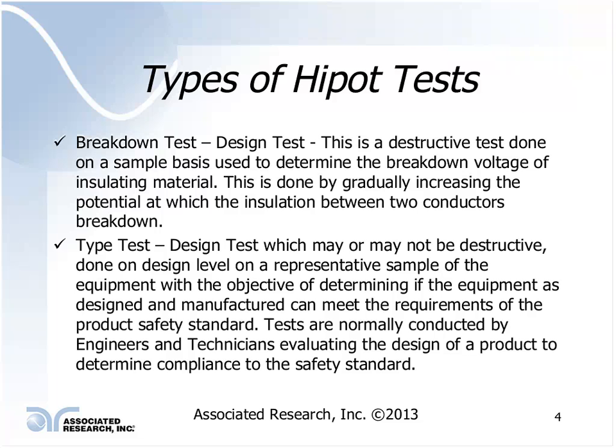What is the category of the insulation? Is it a product that is meant for outdoor use? What kind of pollution degree could be expected with the product itself? And what I mean by that is, is it a dirty atmosphere that your product could be used in?